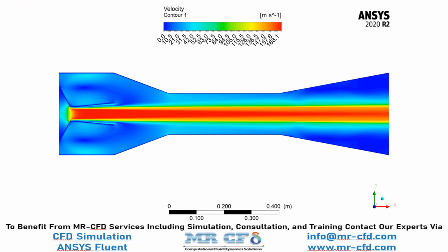Now in this contour, you can see the velocity distribution inside our computational domain. In the middle part of our computational domain, you can see the liquid ammonia passing with high velocity due to its high pressure in the inlet section. And along with it, the vapor ammonia will entrain and exit the computational domain with the liquid ammonia.